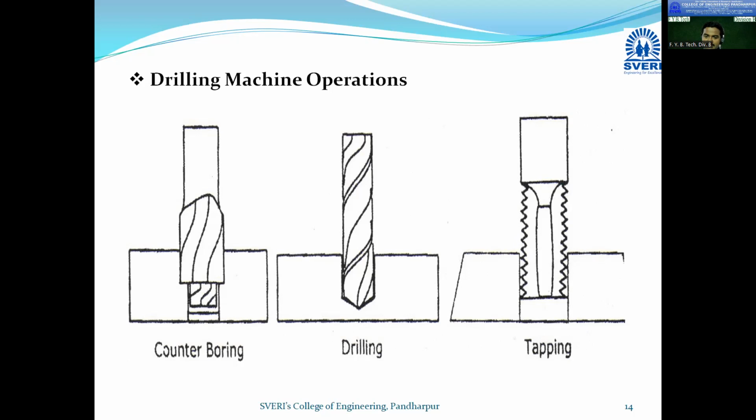Okay. When we want to do drilling, we know that the drilling tool has rotary motion as well as feed motion. You can say as a feed motion, that means you take the tool towards the workpiece, downwards. That is called as feed motion. So we can create a required size of hole in the workpiece. The workpiece can be a metal or maybe wooden kind of thing, right? So shortly, drilling is the process of making hole.